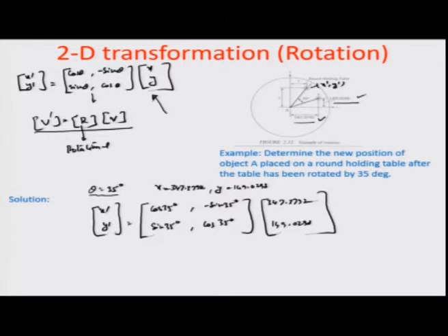coordinates, which represents the initial stage of the vector at point A. So, if we apply the matrix multiplication rule here, the x dash and y dash would come out to be equal to 199.0764 and 321.3216. So, that is about how x and y can emerge into x dash y dash executed through a rotation. Now, the advantage behind this process is that supposing you have multiple rotations in space, that normally is the case when we are talking about solid modeling, where we are having a model and we are turning it around, rotating it in different locations and then replotting it.